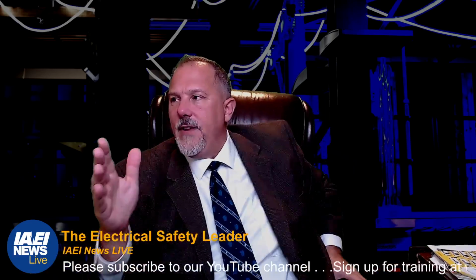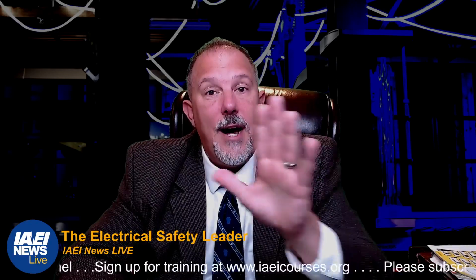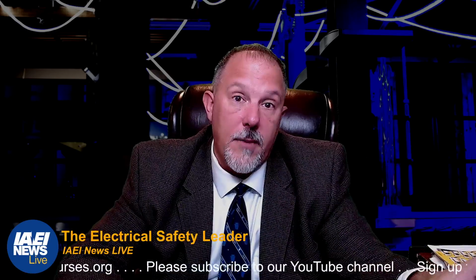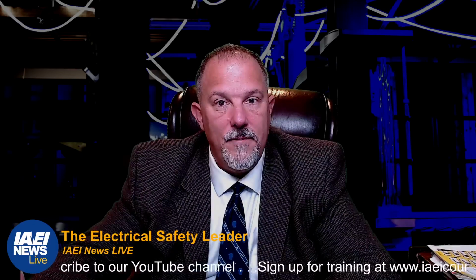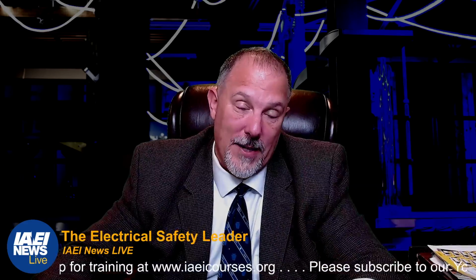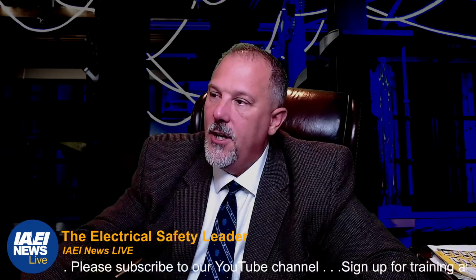So where a breaker is used with an available fault current. So what is a series rated system? And the reason I'm going down this road while I'm talking about 100% rated, because I will series rate to save some money. I will do 100% rated to try to save some money. It may be that the 100% rated breaker and the equipment is less costly than the conductors. But what is really expensive and where it all goes out the door is when you bought the 80% because you didn't specify it correctly, and now you have to change it. Now all of that cost savings went out the door. So same thing on series ratings. In series ratings, remember, you can do a test.